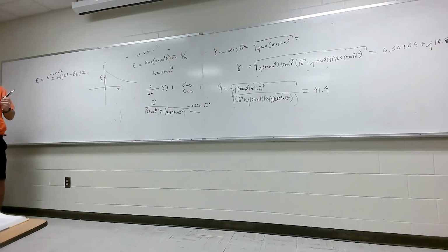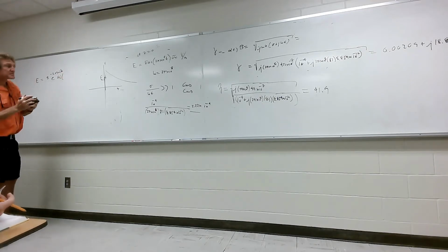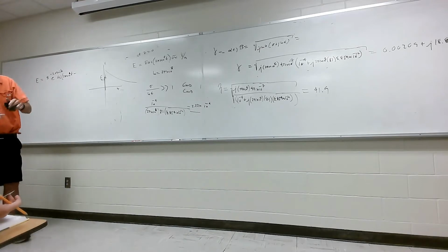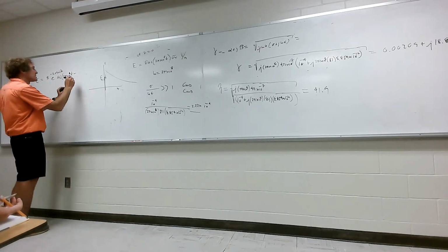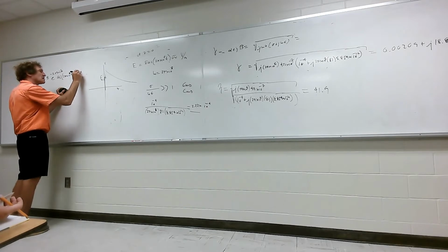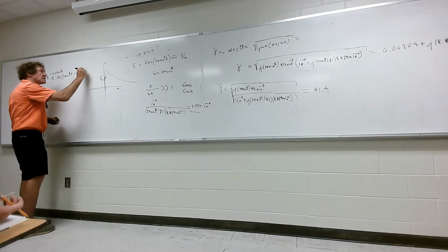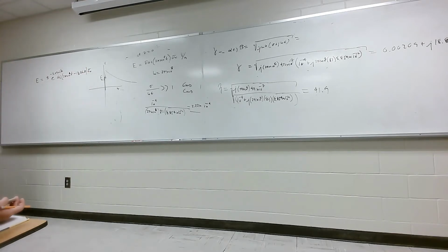I'm just replacing the things. We know omega is going to be equal to 2 pi times 10 to the 8th. Now we put in beta. We got beta is 18.86 z, right? Y'all with me? And that would be in the AX direction. That is going to be the actual E field of volts per meter.